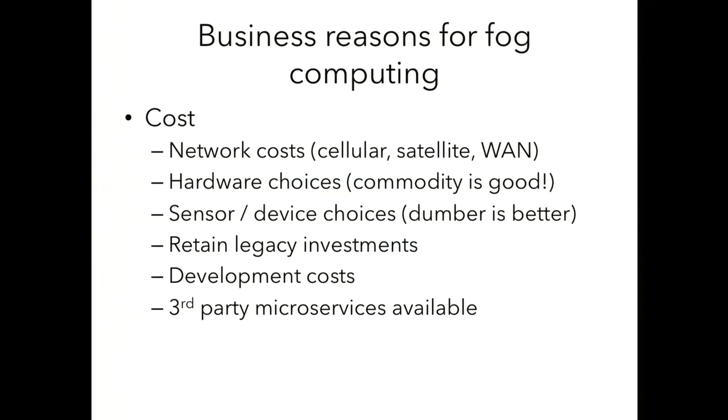You take a picture once a day. Well, one photo a day, one megabyte a day, right? But then do that times 1,000. So you're sending a gig a day over cellular if you've got 1,000 of these sensor nodes out there. Forget about 10,000, right? So the costs start to get astronomical, and you really want to do the processing there on the edge if you can.